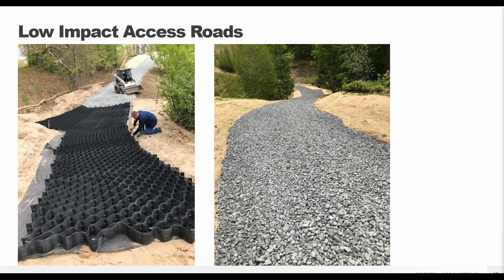And site access roads, both temporary and permanent, are, like I said, a really common application of the GeoWeb system. So as mentioned, really heavy loads can drive on that system so that you can get to wherever you need to, including both tracked and wheeled equipment, without having to build excessively large roads or have high runoff potential from hard surface roads.